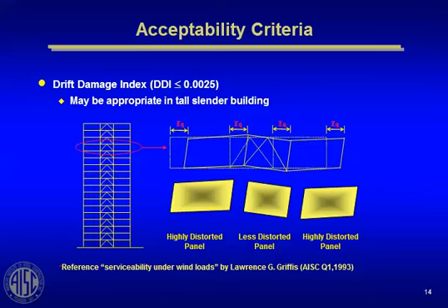And it turns out that in high-rise buildings, that shear strain is not only a function of the displacement of one story relative to the story below, it's also a function of the column shortening of that column on the right compared to the column on the left. That's differential column shortening, also a component that causes shearing strain and therefore damage.